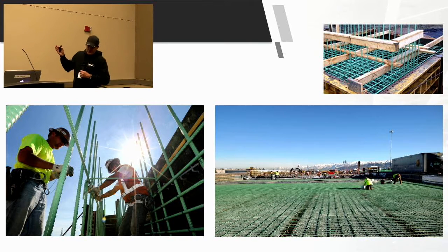The other thing on deck, the spec talks about tying the top mat of rebar down. And you'll get grief every time you tell the rod busters to tie it down, because they'll come back and say they've never seen a mat float, and they float. I can promise you they float. I've seen it. Brand new decks had to be removed because they didn't tie it down, the mat floated, and they didn't have their clearance. So just make sure they tie that mat down to Nelson studs or to panel cables, whatever. Make sure that mat is tied down.